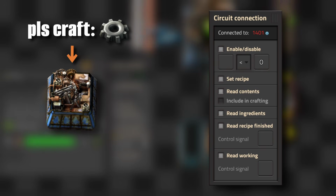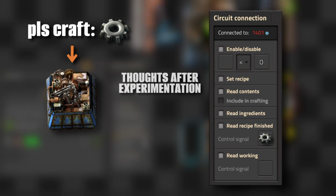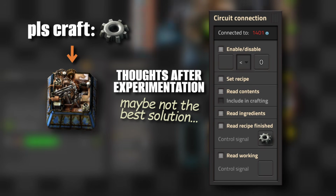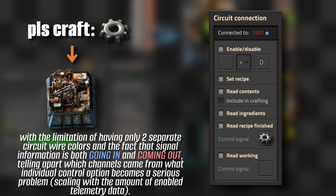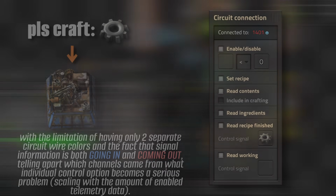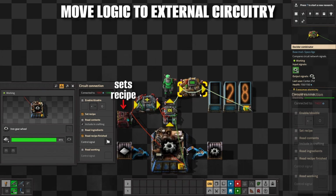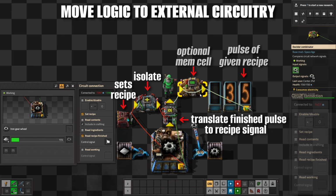What I mean is that the machine translates the current recipe information into this signal slot automatically. While running a few tests, it became fairly obvious though that making both channels the same type isn't such a good idea, since outgoing signals now lose information clarity, making it hard to tell what option sent out which value. If still desired, some simple external circuit logic has no problem to replicate my desired feature to give me a single pulse of the just manufactured piece.